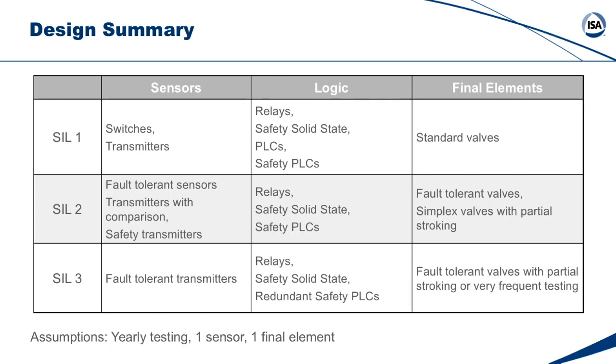And I said, you don't have such a requirement. You have someone somewhere in your company who went to a seminar and heard SIL 3 is the highest without having any understanding of what that means or what it costs. And he comes back to you and tells you to do everything for SIL 3.